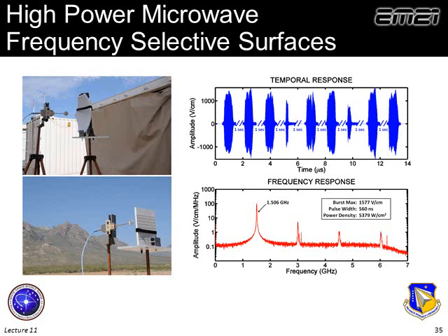Well, imagine what would happen at a few megawatts or gigawatts. So we're adopting an all dielectric approach. We're using guided mode resonance filters to do that, and we've already demonstrated some really, really high power surfaces. And we've also put engineering into these to broaden their bandwidth and their field of view all at the same time. So that I know of, here at UTEP, we have the world's highest power frequency selective surface.